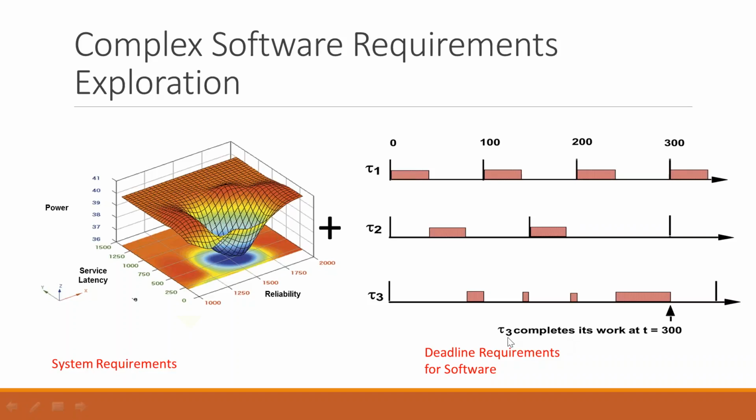So for example, this particular task T3 was to have completed at about 230 seconds, but ended up taking 300 seconds. Why? It had nothing to do with T3. In reality, a higher priority task showed up right at 200 and started executing before T3 could execute. As a result, T3 was preempted and waited until it could complete down here at 300.